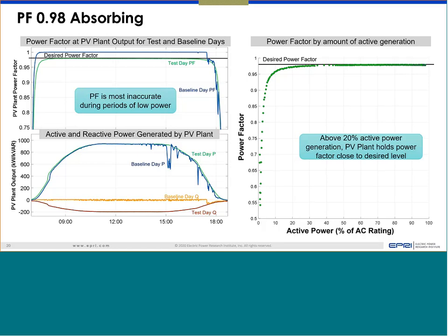So oscillating behavior, but you will not see a sustained high or low Q. Pretty much we have seen 0.99 and then a third digit of power factor maintained by the inverters if you ask it to operate at unity power factor, except if the inverter is using a reactive power based islanding detection mechanism, then you may see some oscillatory behavior across the zero line.